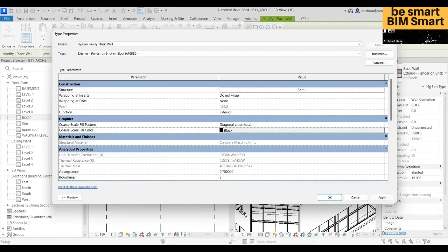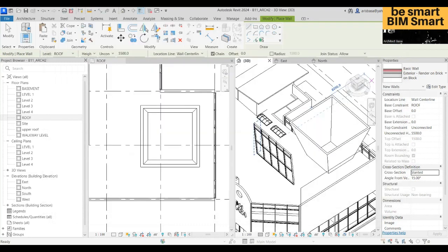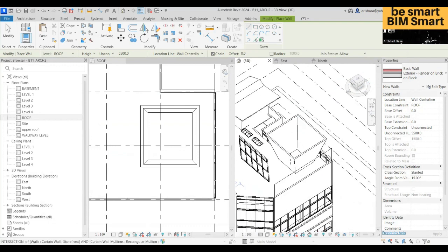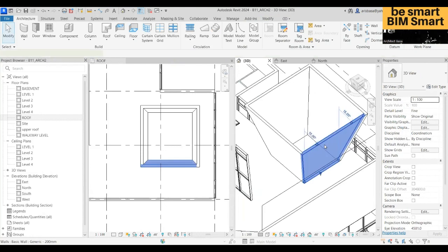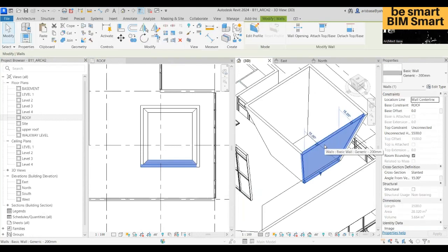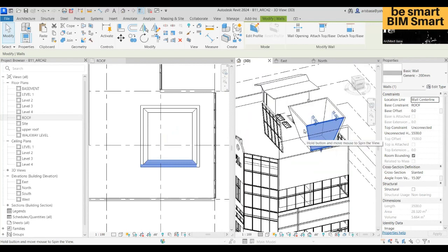I think it's better we create another small building next week, maybe a security post or something using this type of command, right? Once we learn how to create a tapered wall, then we need to learn also how to connect tapered walls. You have to connect it like this, and that's another thing. So not for now, we'll do that next week. Because these slanted walls are easy. The same cross section, it doesn't taper, so it easily connects to each other. And of course, you can replace that with a storefront as well.